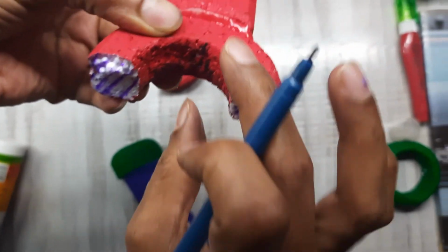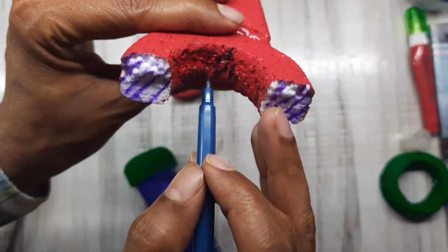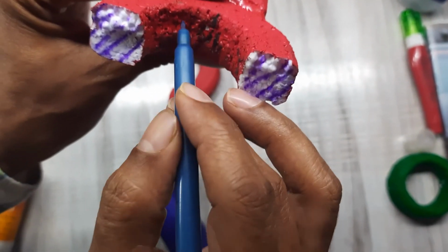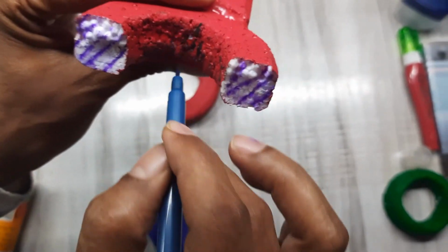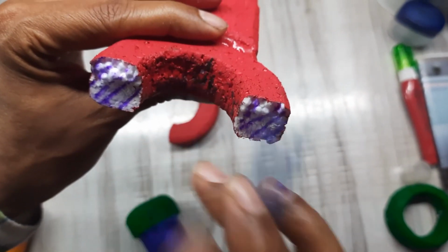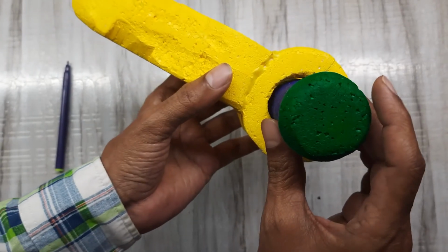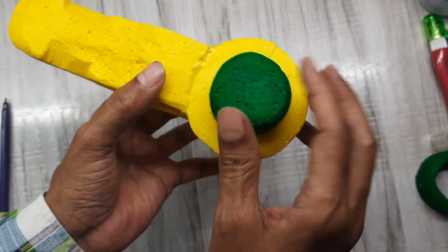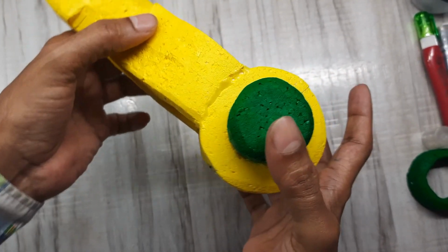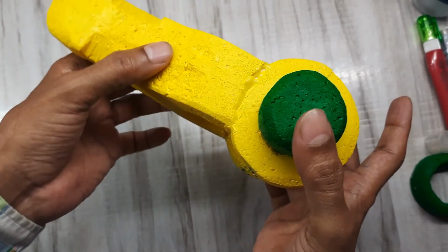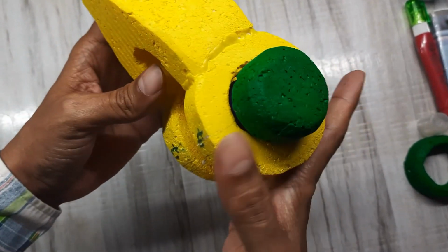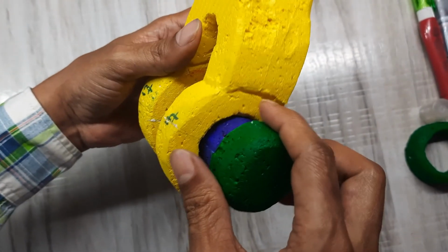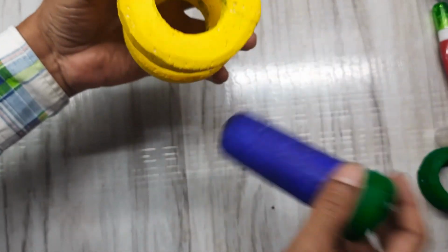So this region is nothing but D1 into T. That will be the crushing area, that is called the resisting area, D1 into T. Now, failure of double eye in crushing. Again, I am just inserting it, and we know that there is a possibility of an angular movement, due to which the crushing action will take place between the pin and the eye, that is the double eye, at this portion.